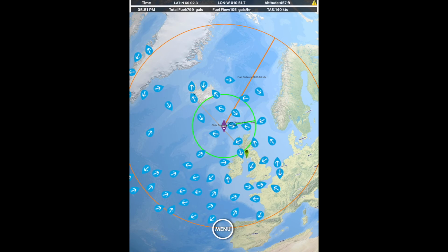We demonstrated earlier using Ergo 180 as a pre-planning tool, so the pilot will have improved situational awareness of the aircraft fuel and oxygen range rings based on tabulated information. The user can depart with the app in a manual operation. This will be recognized by the yellow triangle located in the top far right corner in the app window. Ergo 180 is programmed after reaching an elevation of 500 feet above GPS-sensed ground elevation for the total fuel to start counting down.